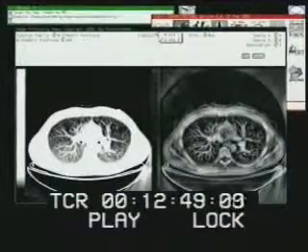Right now we're interpreting what's in the frame buffer as full color, but we can look at any individual 8-bit channel of the least significant 24 bits of the frame buffer. It's a 32-bit deep frame buffer. So these are really grayscale images, for example, and so we'll just look at the red channel, or the least significant 8 bits. I'm going to load up an 8-bit image and perform some of the functions from the image processing library.